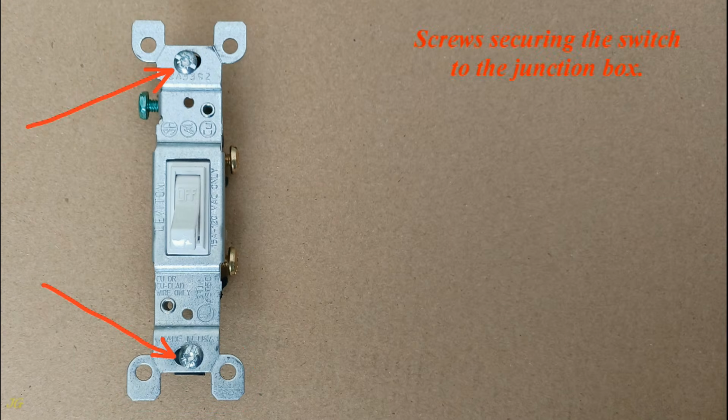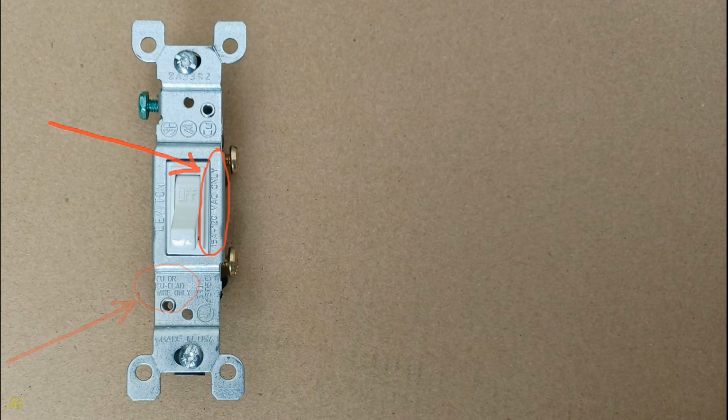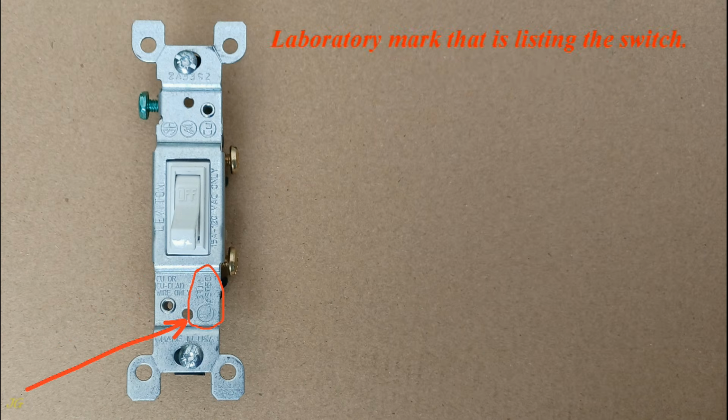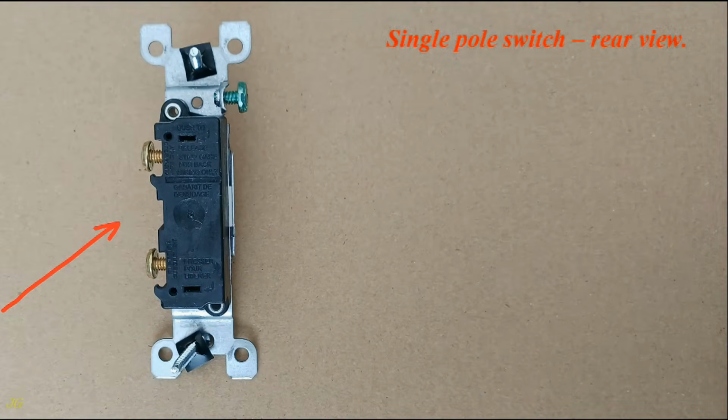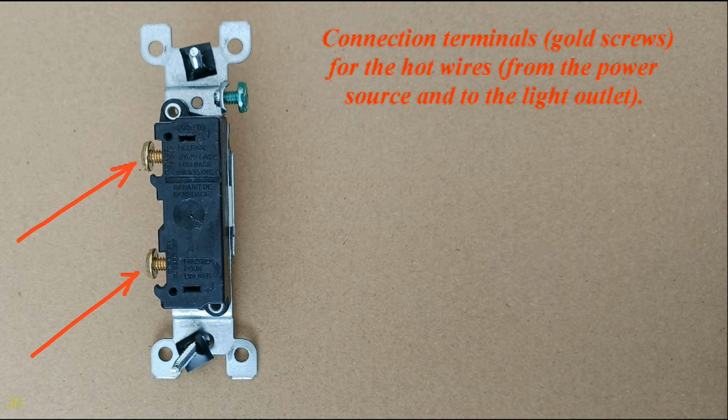Screws securing the switch to the junction box. Holes for screws securing the switch wall plate. Rating of the switch. Type of wires allowed to be connected to the switch. Laboratory mark that is listing the switch. Single pole switch, rear view. Terminal for the ground wire connection, green screw. Connection terminals, gold screws, for the hot wires, from the power source and to the light outlet.